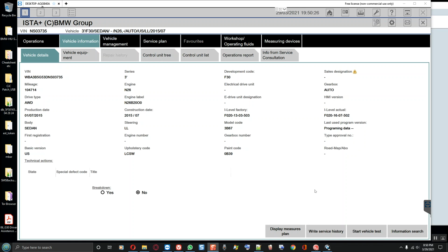My other thinking is, using that pinout, and if this is easier, I may just go this route. I've been adding wires for these headlight modules and everything, so I may make 2 wires and pin them into that 19 and 20 on the ICM and go to the ACSM module and connect them there and see if our fault disappears or not. And if that works, then we may just say screw it and do that. You know what I mean? Yeah.